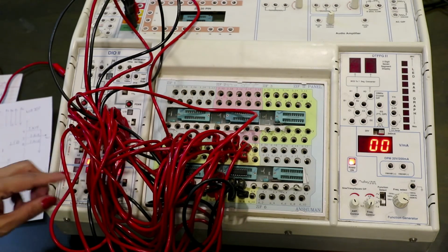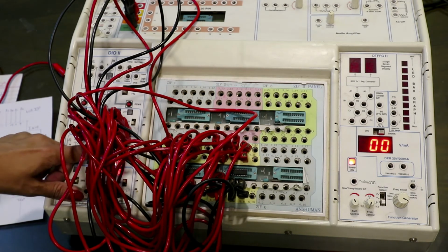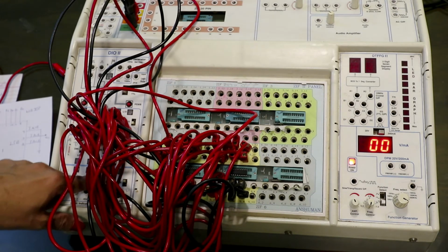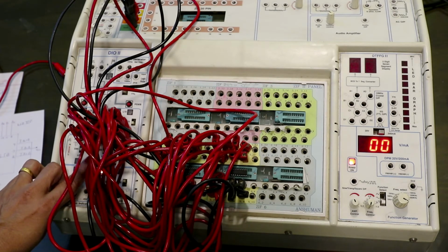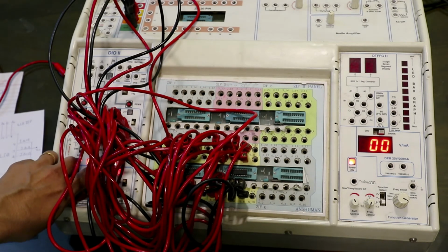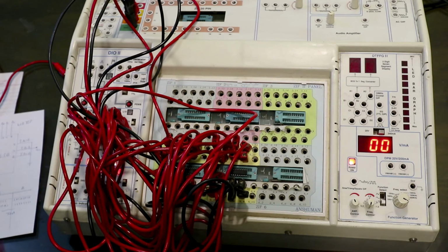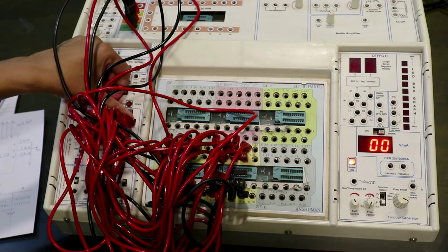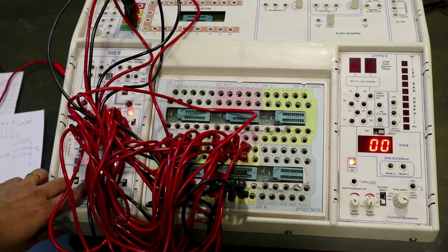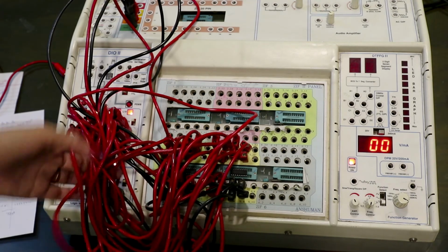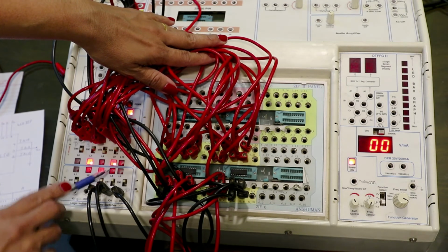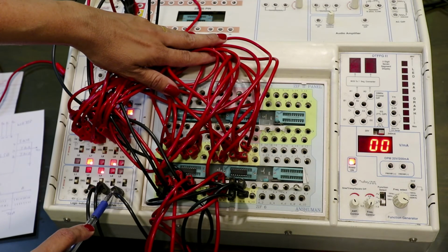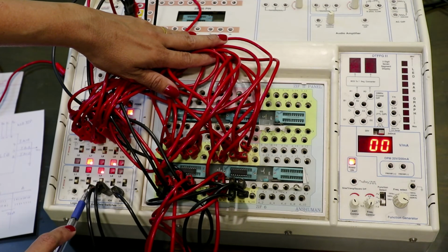Now any other case, suppose I consider some other combination. Suppose I consider 1 0 1 0. So for A I'm going to take 1 0 1 0, right? And then for B I'm going to take all 1. So in this case, A is less than B, output should be high. So see here, we are going to get the output A less than B. This is the third combination, because this one is for A greater than B, this is for A equal to B, and this is for A less than B.